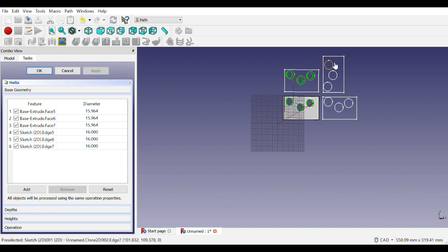Now I can also click more, okay, but usually when I CNC, I like to do one part and then do the outer edge, cut it out. That way while the machine's moving, I can take this part out, inspect it. If anything's blatantly wrong, I'll just stop the machine and save my work material. If you don't want to do that, you can select all the helixes at once and drill holes into your entire sheet of material, okay?